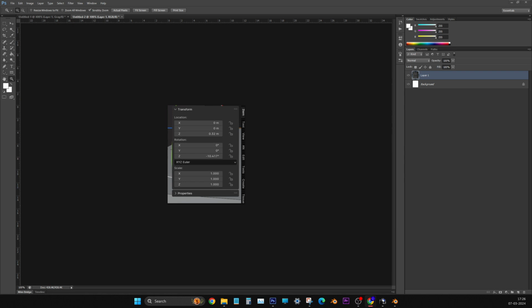Those vertices, we have to bring them down a little. No, no. What is this? That selection, in the z-axis. Bring it down a little. Yeah, enough. Now select only one vertex in that part. Select only one vertex. Now we have to snap it. How? Snap means, you know, when one vertex is nearing the neighbor vertex, it will just snap onto it.